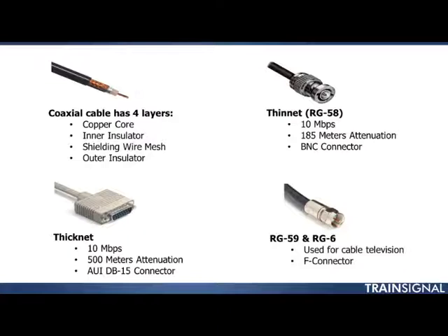And the F connector is, just as you see there, where basically you just slide the connector over the peg that you're connecting to. Now, in some cases, you just slide it on. In some cases, there are actual threads and you screw it on. But the bottom line is you just slide over the peg and you are connected, as long as that copper core makes it into the hole on that peg.